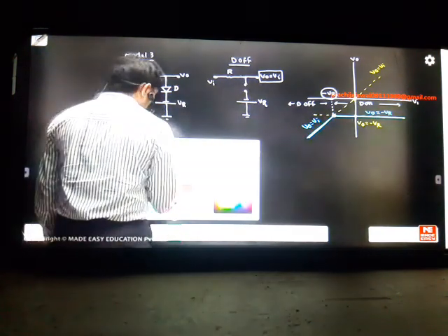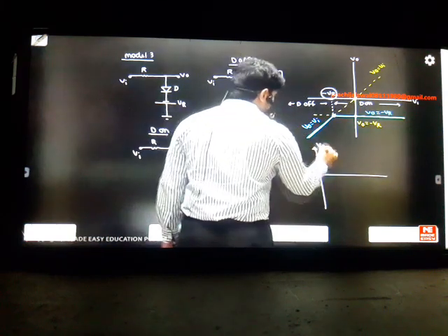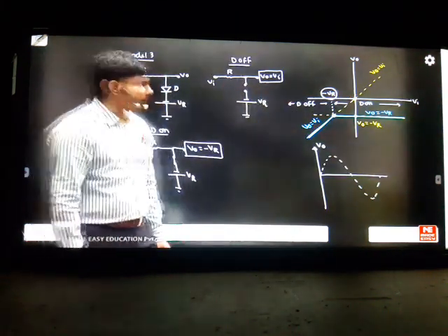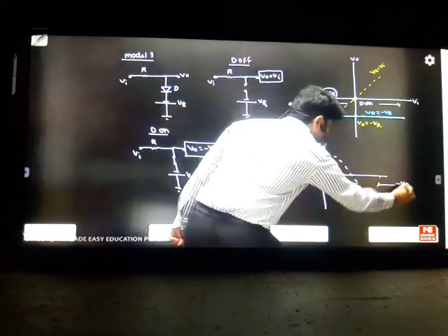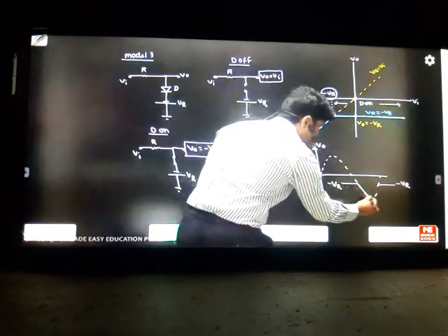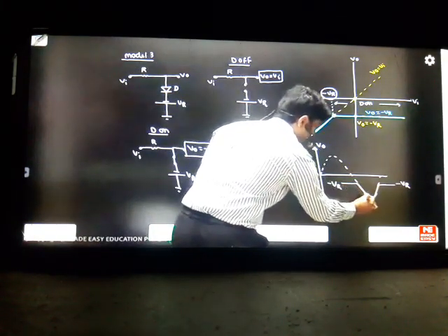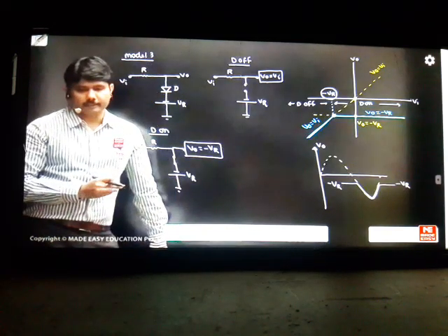Everybody can enjoy it. So can I have the output waveform seeing this diagram, seeing this transfer characteristics? How to write a waveform? Seeing this transfer characteristics, this is the part we are following, up to minus VR. So you take these lines like this. This is minus VR. Below this you are following; above that you are not following. So only below you are following this part. Maybe this is your waveform. Below you are following; above it is a constant of minus VR.